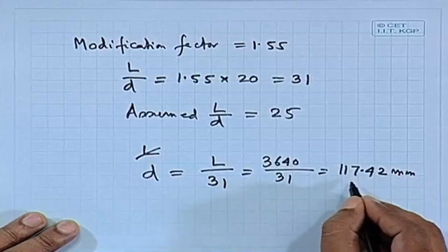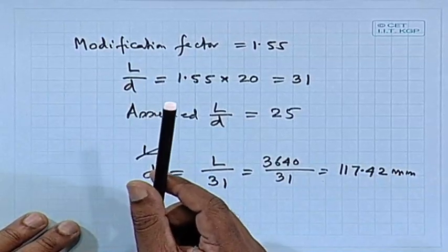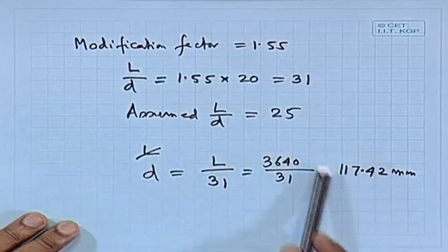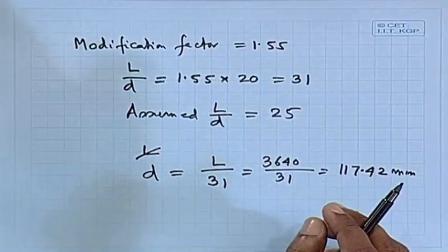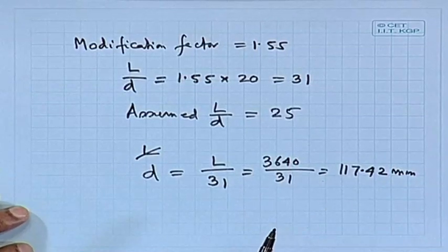We have seen that D is coming as 90, so in this case we can take 120 as the effective depth. Anyway, let us complete the problem here. It means the solution is not economic; it is safe but not economic. In that case one can do the next trial and modify the section.